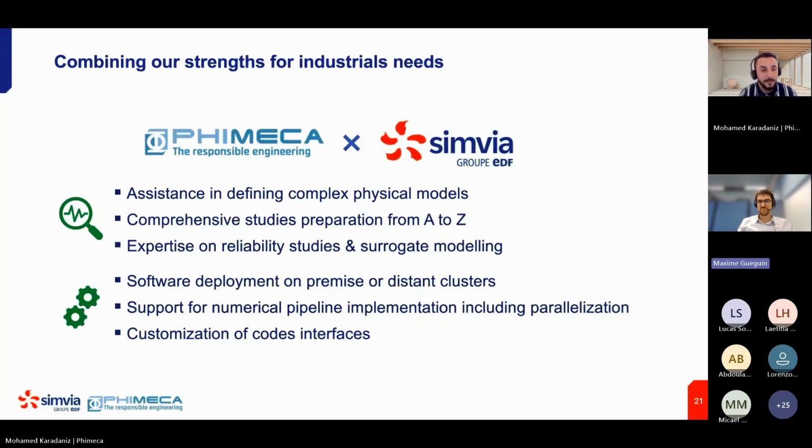Okay, great. There are some other questions about Persalys, but I think that Usama from Phimeca gave some answers about the fact that for each run that you launch with Persalys, you need to have a Python file and a COMM file for each point of your design of experiments. So I think that's the case, and maybe you need to clean a little bit when you are starting to work with this.